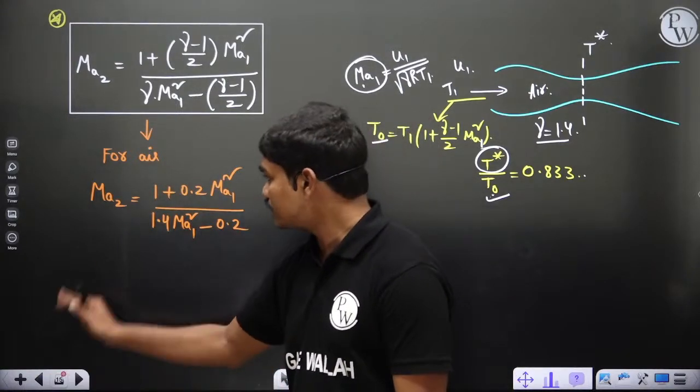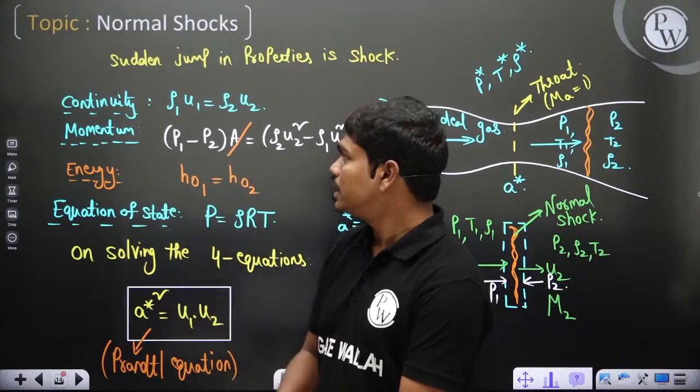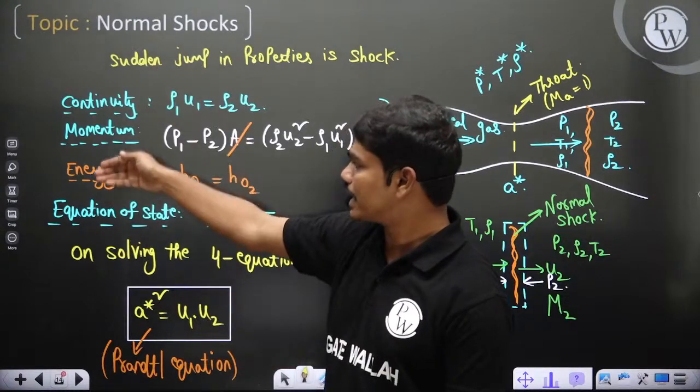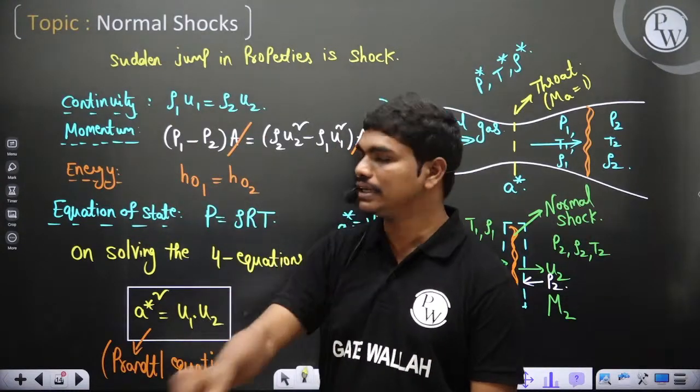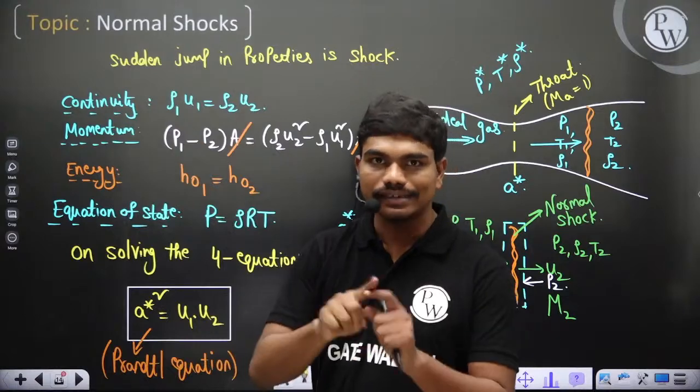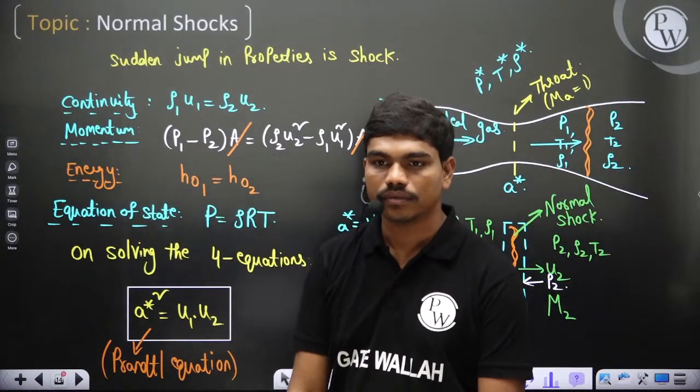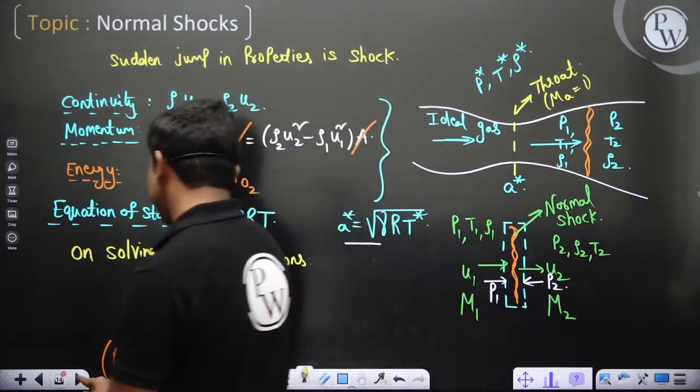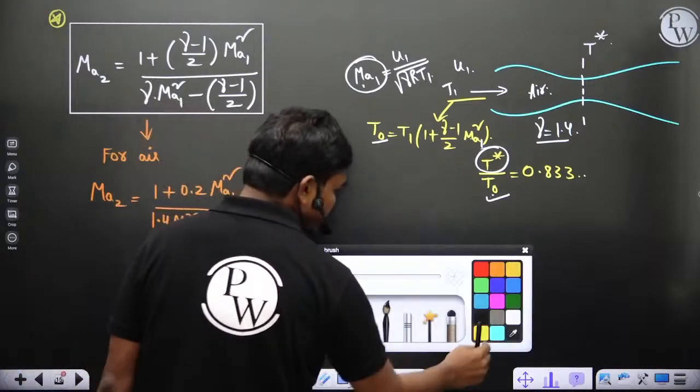And normally, based on these 2 equations, we plot 2 different lines. If you plot mass and energy, we plot the Fanno line, and mass and momentum gives the Rayleigh line. Normally there are 2 lines where we plot HS curves for shocks.